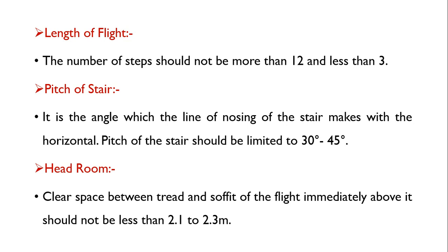But at this level, just remember, pitch is the slope made by the flight or stair with the horizontal. In simple words, the pitch of the stair should be limited to 30 degree to 45 degree. It should not be less than 25 degree. Please remember this, very important, because it's asked in various types of exams and competitive exams also. The range given is 30 degree to 45 degree and the minimum is 25 degree. It should not be more than 45 degree.